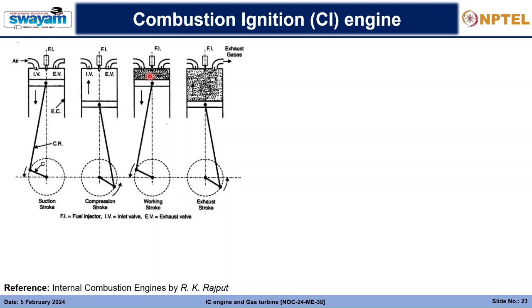This atomization is very important in order to ignite the fuel very fast and to reach very high pressure and temperature in a very short time. That's why the atomization process is very important, and the design of a fuel injector is of very high significance, and you will get to know later how to design a fuel injector and how it works.